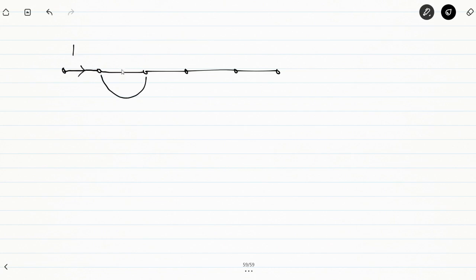You had 1 here, you had 1 by s here, you had minus 2 here, you had 1 here, you had 1 by s plus 1 here. Instead of 1 by s plus 1, we'll be having 1 by s and you'll be having a minus 1 in the feedback path. And you actually already had another loop path that is represented by minus 5. And the gain of this forward path is 4. This is your y and this is your u.